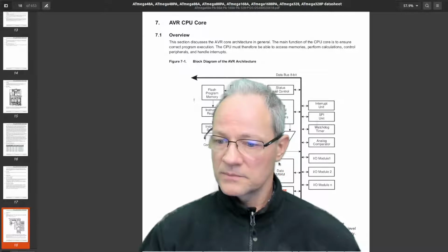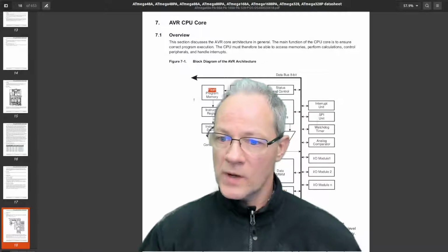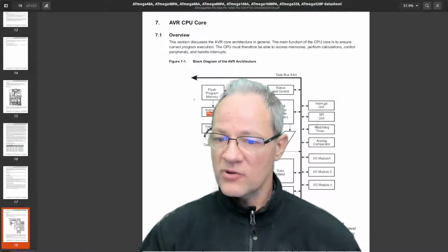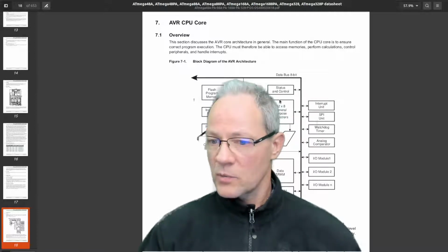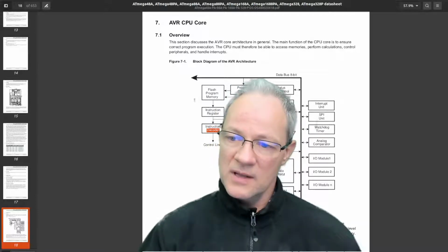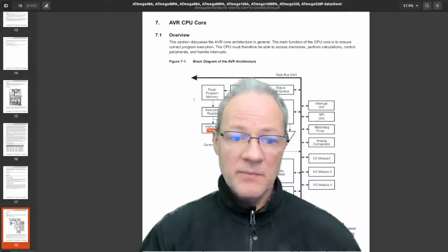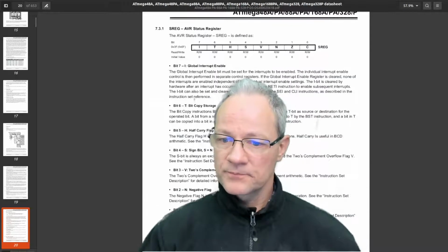Or EEPROM as well. All right, so as the program counter counts ahead, we can read instructions one by one. They're going to get decoded, and these decoded control lines will be connected to the rest of the system and drive what should be done. For example, which register should we read into the ALU, where should we write back the result, and things like that, right? So that's about the CPU.